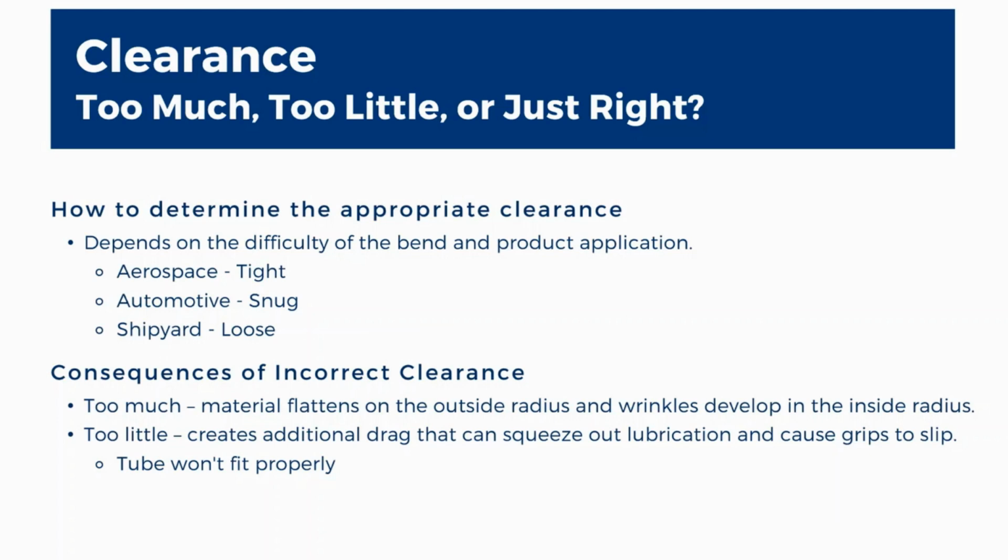A keynote about the material specification: the range of variation of the dimensions of the tube allowed by the spec can exceed the automotive and aerospace bending clearances we discussed above by 2 to 3-fold. Understanding the sizing of your material or having a mandrel size to your specific material can save you a lot of unexpected issues, scrap, and cost from one lot of material to the next. When you're using material with weld seams, it adds another layer of issue to discuss outside this presentation.